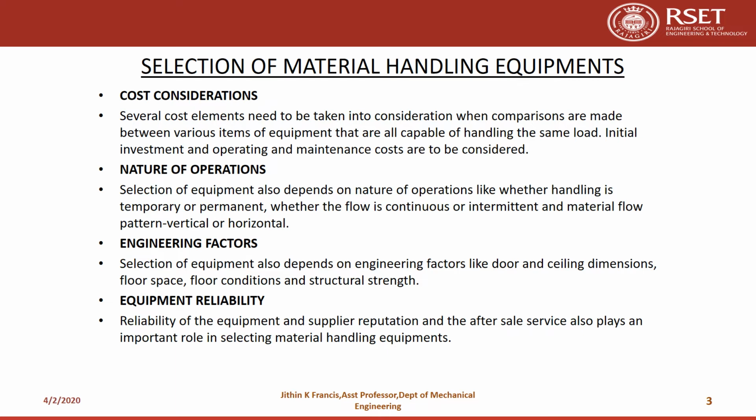Then the nature of operation. Suppose you have an operation of a temporary nature, you need not go for a permanent one. That means you need not purchase a material handling system. Rather, you can hire a handling team. For example, if you have to lift a heavy load of a temporary nature, you can hire a crane service. That is fine. Then another factor, the engineering factor, also contributes to the selection.